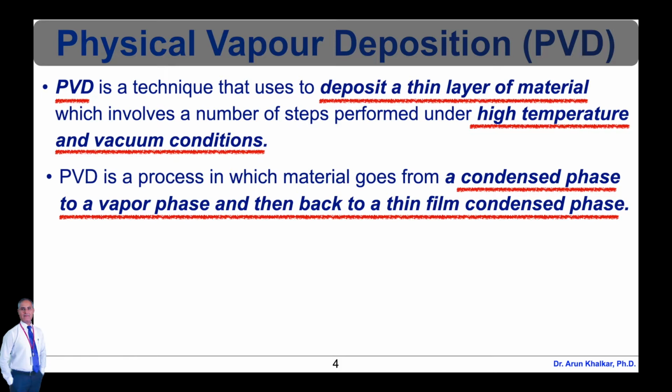Physical vapor deposition is used in the manufacture of items which require thin films for mechanical, optical, chemical, or electronic functions. First, a solid precursor material is gasified, typically through the use of high-power electricity or laser. The gasified atoms are then moved into a reacting chamber where the coating substrate is located. Source material atoms then stick to the substrate, forming a thin coat.